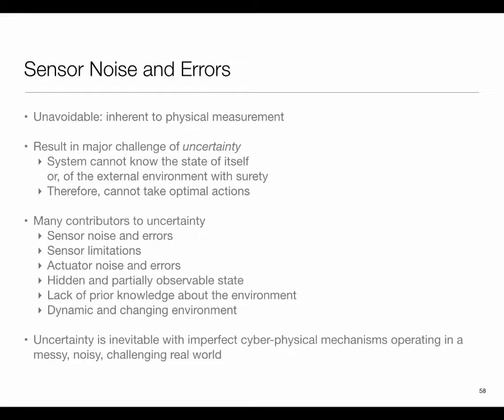You would see that there is a lot of front-end circuitry put around sensors to clean up this noise. So let's take the ECG example again. A very common problem with ECG signals, particularly in hospitals, is that the electrode gets displaced, or when you are moving, there are additional electrical signals. Or, for example, ECG leads may pick up the 60 hertz signal from the electrical wiring.